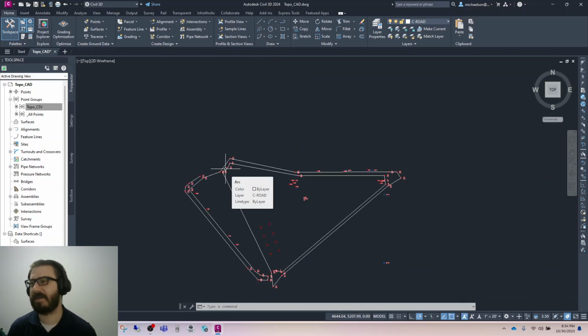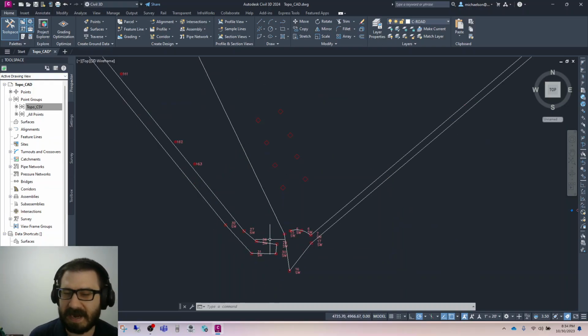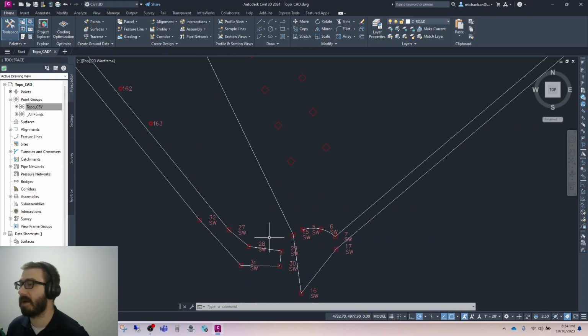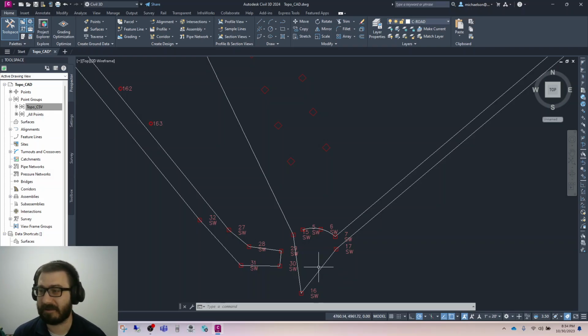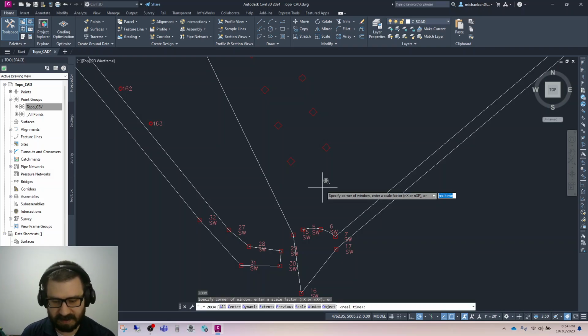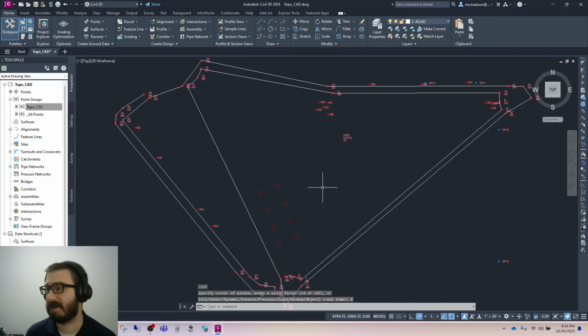I think there's enough here that you could compute the rest. I know that some of these line works are probably not correct, but again, this goes back to the field notes. The field notes that you take indicating what corresponds to what are incredibly important. For our purposes, I'm actually just going to go with this. I know it's not accurate because I know the sidewalk right here doesn't look like this in Buskirk Field, but for the purposes of this demo, I think it's fine. So let's zoom extents. Now what we need to do is process our topographic data.